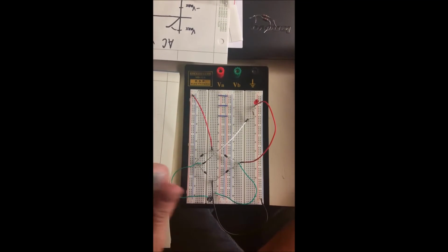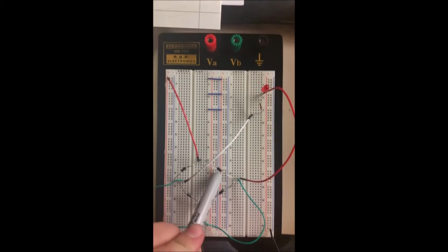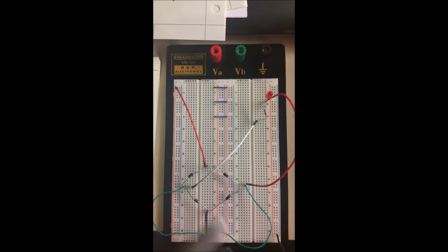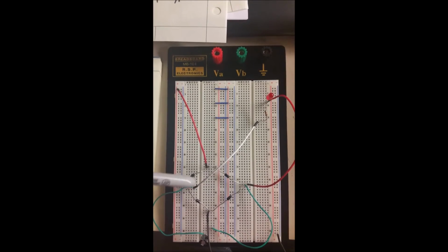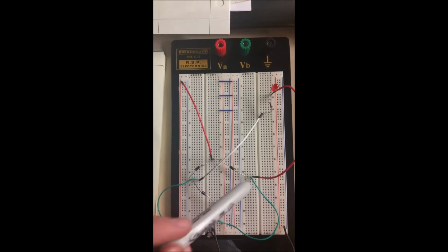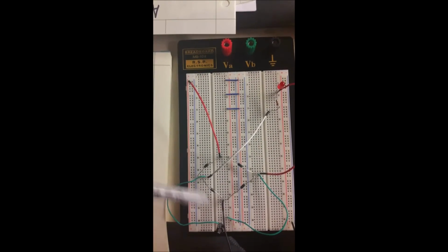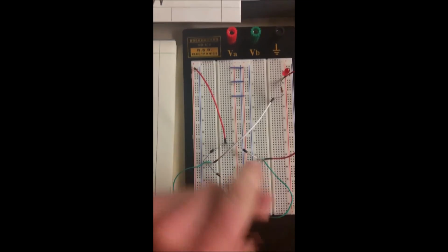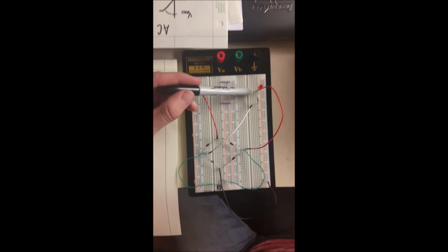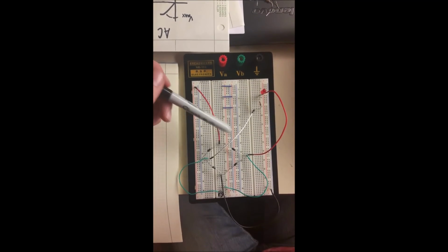These diodes are only going to let the current pass one way. There's a line on the diode, and it's going to be the way which current's going to go through. So this way and this way on this one. These will never be able to pass current, leaving a potential difference across here. So this is going to be your positive and negative of DC. And in between them here, it's going to have the load, and it's going to be anything. We just got an LED hooked up, and it ought to work.